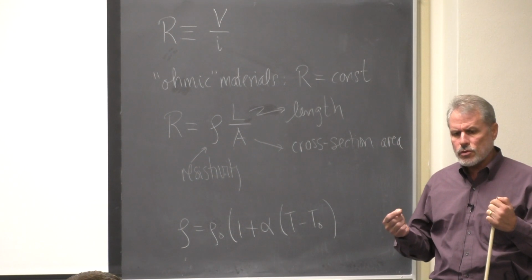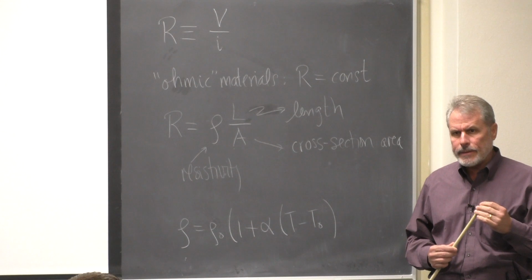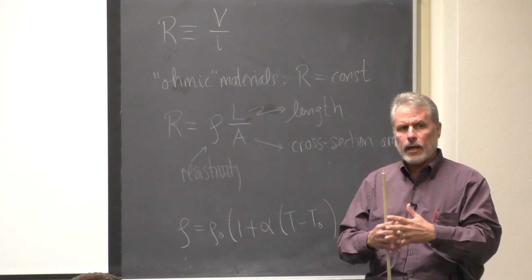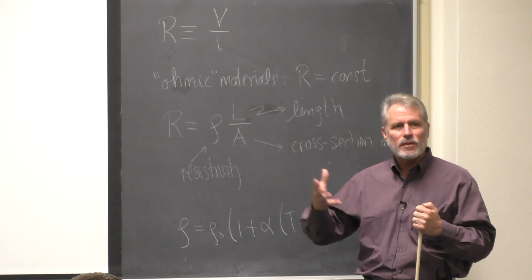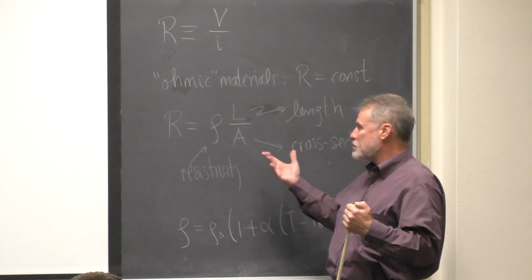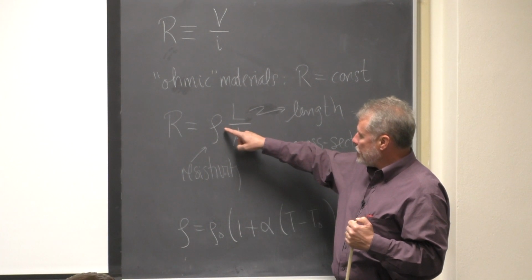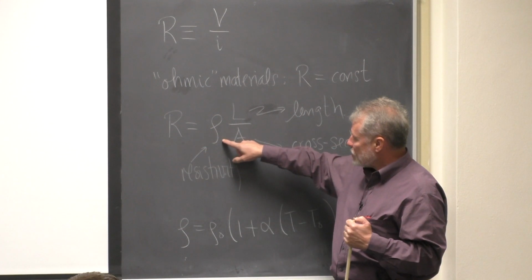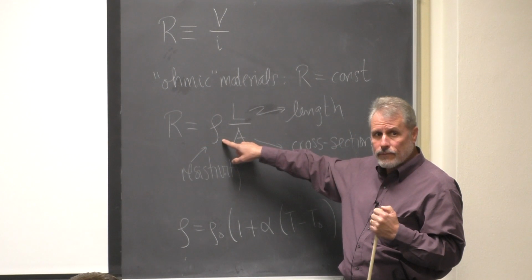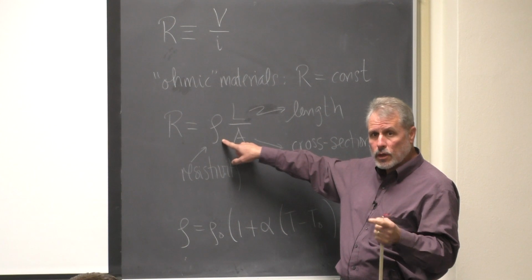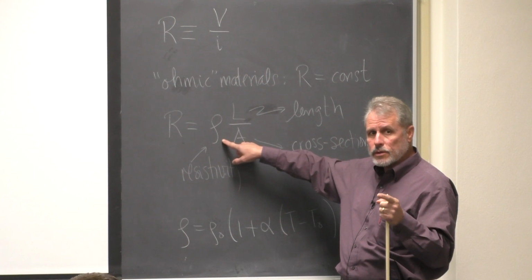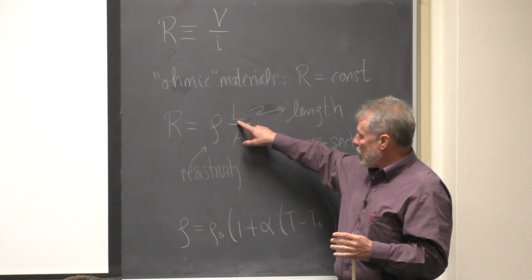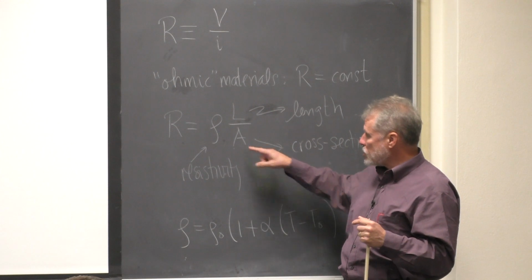We also introduce the resistivity of a material, which is a local property, sort of the resistance per unit volume, or resistance per unit length. In this way, the resistance is determined by the resistivity of the material, which is a function of the temperature. So when you look it up in tables, you always find reference to a particular temperature value, say 20 degrees. It also depends on the length of the material and the cross-sectional area of the material.